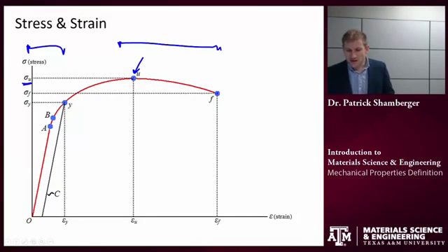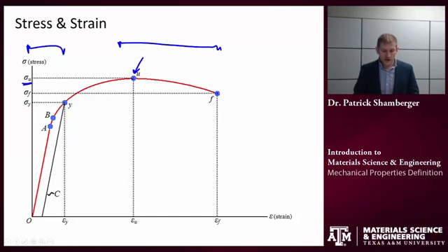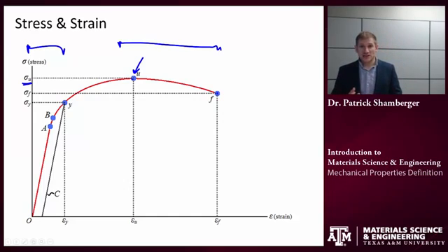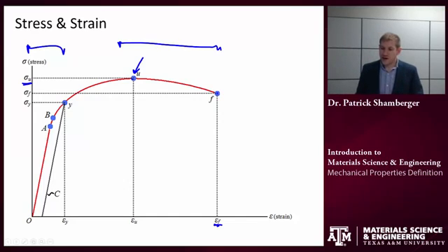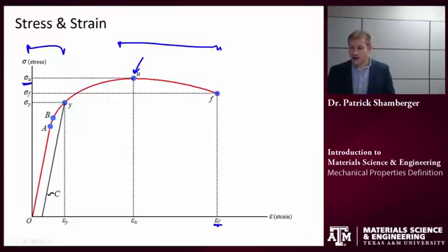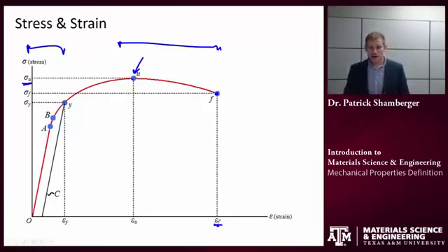And finally, this is called the failure point, the failure stress, failure strength. This would be the failure strain point. And this is when the material actually breaks entirely on you. So this is a very important point in terms of what's happening under extreme plastic deformation.